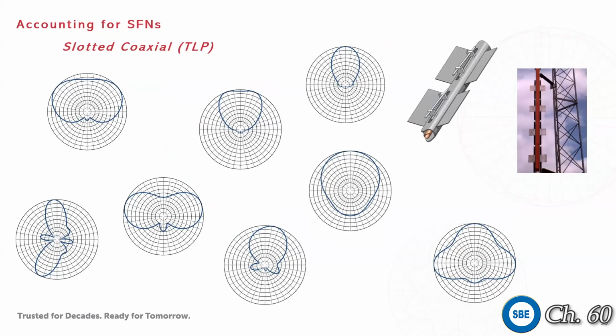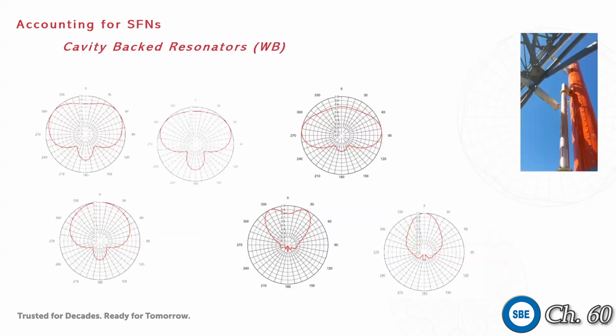The downside is that they have a limit to their channel range. If you need something that has a real high front to back ratio, we produce a couple of these cavity back radiators, and these are also fantastic. Again, real high front to back ratio, and they're also particularly well suited for wideband situations. So it just depends on the application and what you're looking to achieve.